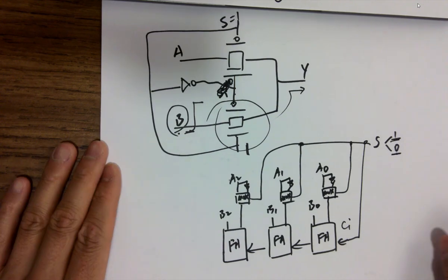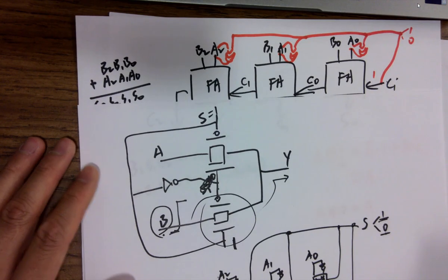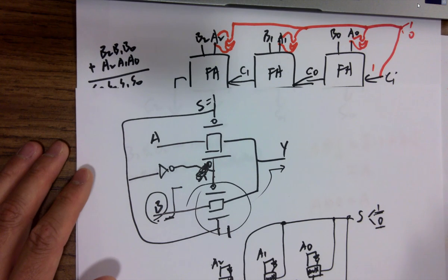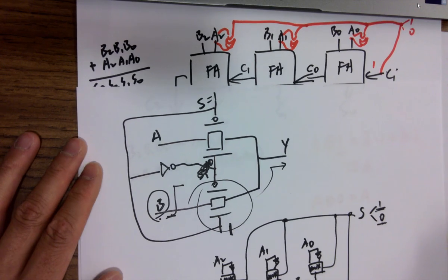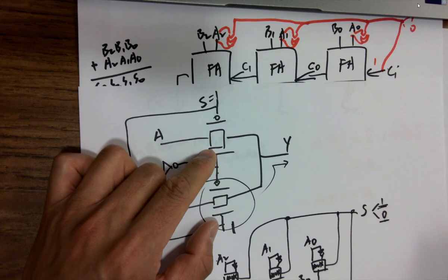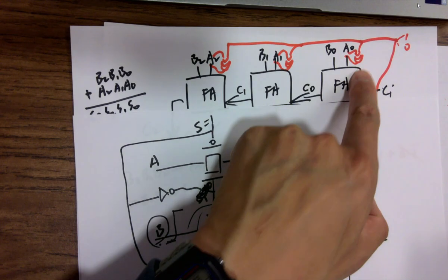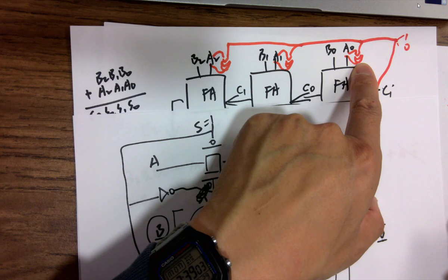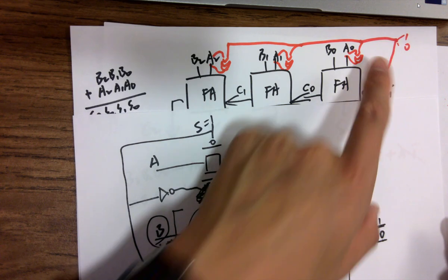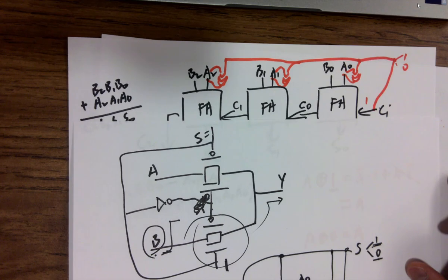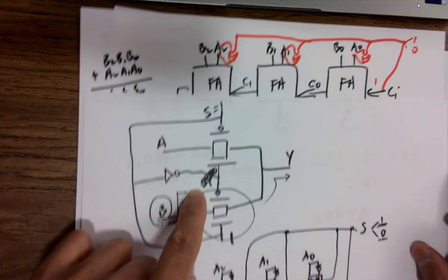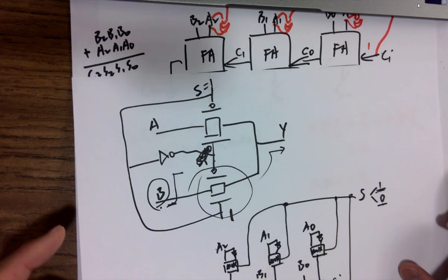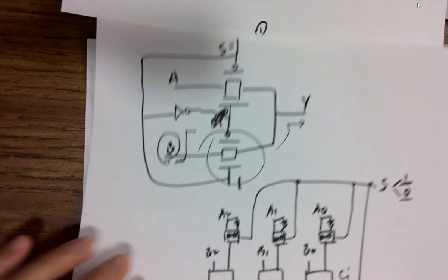Which one's easier? Which one will take less space? Which one's better? Mux or XOR gate? Mux, why? Only 4 transistors. Remember, the XOR gate is just one gate, but actually it has a lot of transistors. Even for the AOI logic one, and even for the stick diagram one, it's still pretty big. I think that's why we picked up the mux for the subtractor for the final lab, the 2-week lab. Any question on this before we move forward?